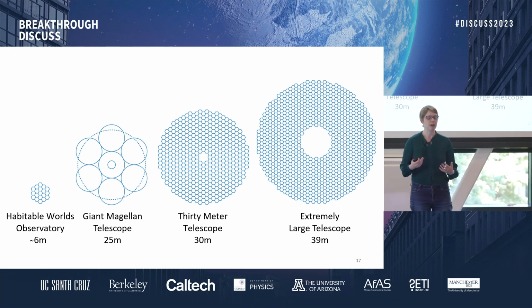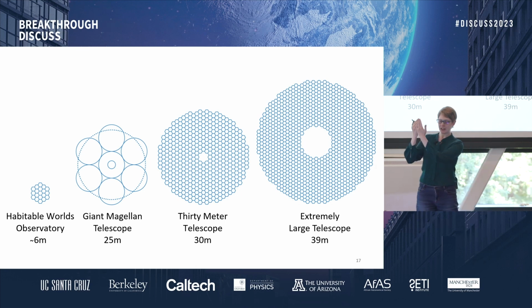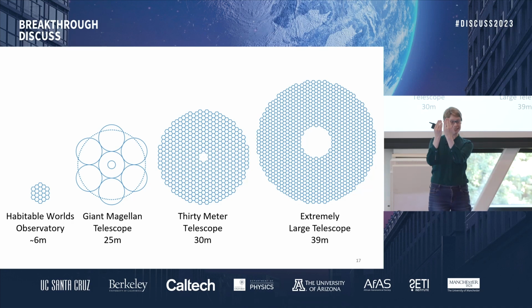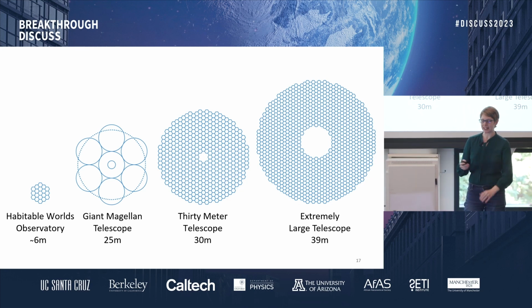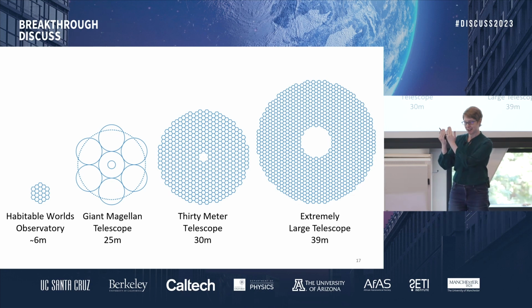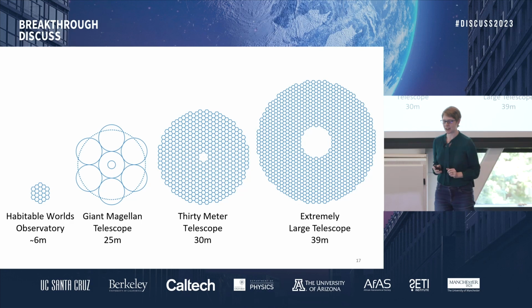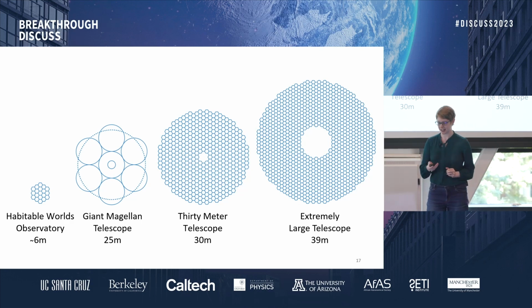And this is an issue, potentially, for high contrast imaging, because if you have incorrectly moved the segments relative to one another, so let's say you'd like to have your segments perfectly aligned, but in actuality, they have some offset to them, that will hurt the performance of your coronagraph. So for something like Habitable Worlds Observatory, you need picometer level control of those mirror segments. That's extremely challenging. On the ground, it's not quite as grim. We're dealing with nanometers and tenths of nanometers precision.